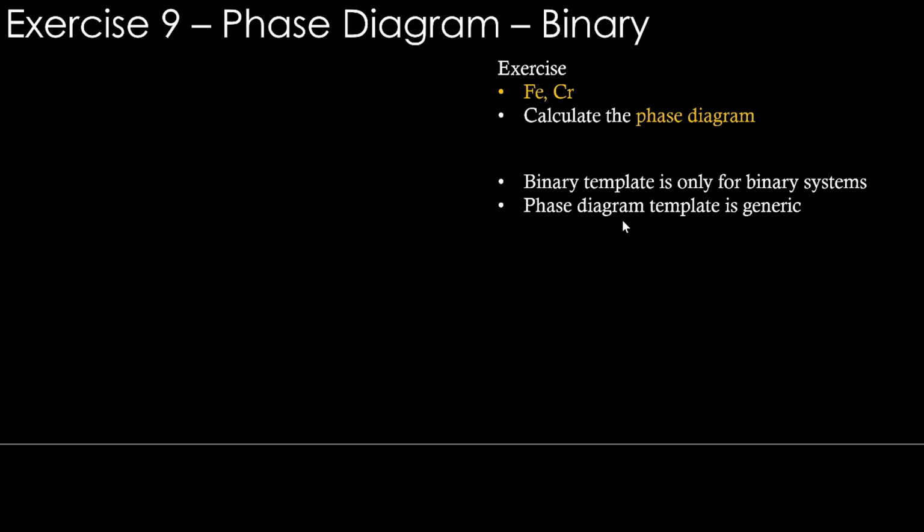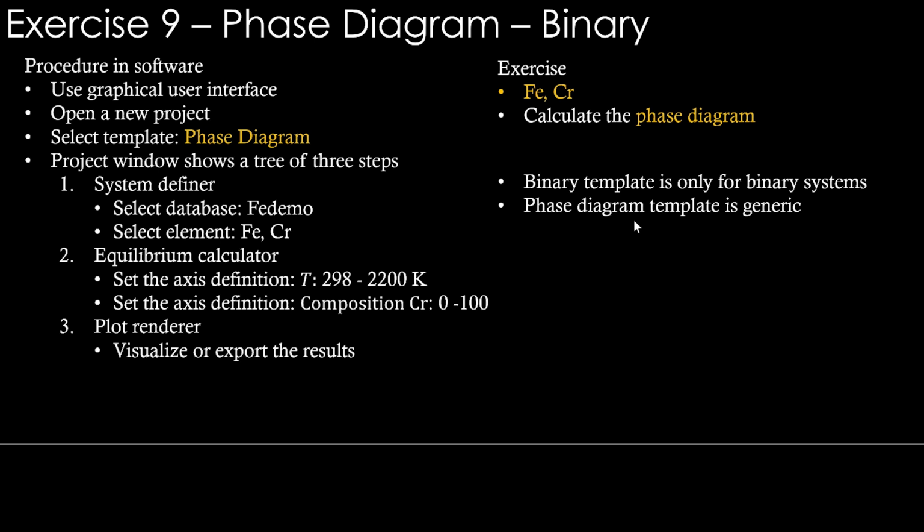Right now we will do a similar exercise to the one we did in the last class, but here the exercise is to make use of this phase diagram template. That's the reason why we are doing this. So it's not a repetition, it's a slightly different one. To do that in Thermo-Calc software, use graphical mode with a new project, select template phase diagram.